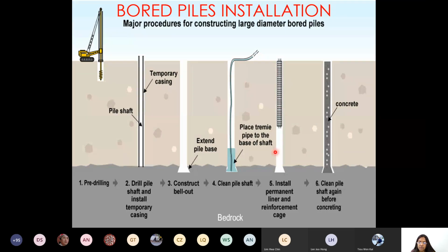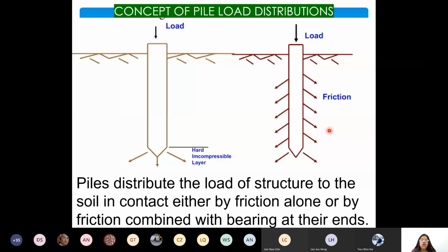If it is a reinforced concrete pile, put the reinforcement inside, then pour the concrete. Do proper compaction, construct layer by layer so that the concrete is settled properly.